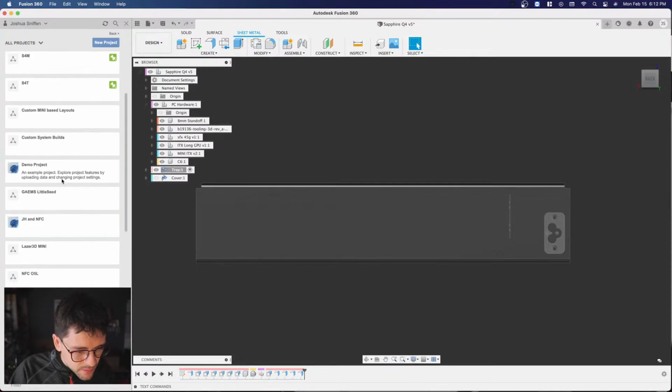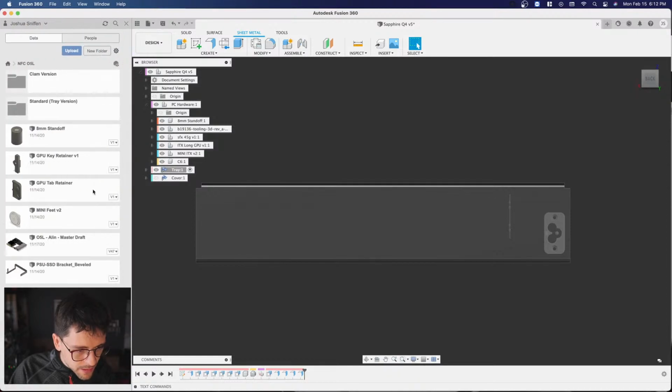Maybe it's here. It's 3D printable retainer keys. So instead of having to worry about specific bins for the tab to mate up with the back GPU flange and having to have punched, okay, they're called lance operations for those little keys to be held back into. Now we can just have straight up cutouts and 3D print a little part and bolt it together, and it's super solid. Let me show you what it kind of looks like. I don't know why this didn't unplug.